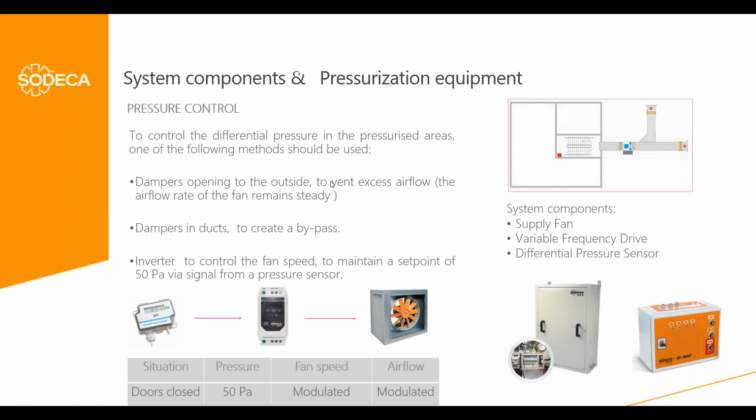In addition, other risks of these systems with dampers is that they work quite good between 2 points, minimum airflow or maximum airflow. But if we have intermediate situations, as we have in part 6 for class C, D, or as we have in part 13, if this final exit door is not ensured to be fully closed, then these dampers cannot properly operate in 3 positions. They operate properly in 2 positions, but not in 3 positions. Okay. So, well, it's not clear, these systems. We have also this possibility with dampers together with the fan to make like a bypass.